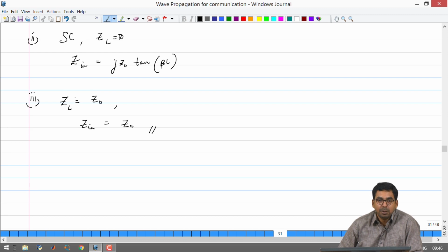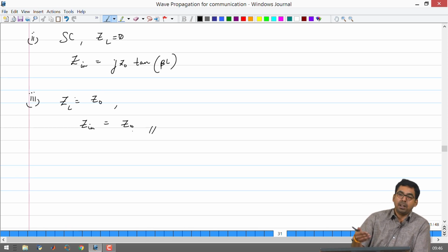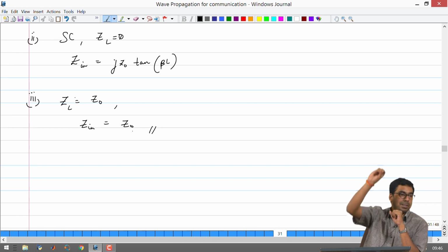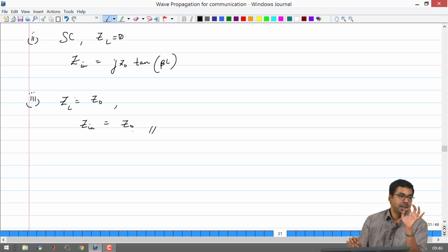The program that we have written, you can always substitute a cosine or a sine and try to see what happens. Here, mind you, we have considered only the spatial distribution. We have still said that with respect to time, it is going to be time harmonic or periodic. So, it means that even though you will have some places in your transmission line having non-zero voltage, with respect to time, it will go to a maximum and then go to 0, but the nodes where it is 0 are going to be fixed all the time. So, some small things will appear only if you take that simulation that we had already done and plug in a cosine or a sine just to understand what that means.